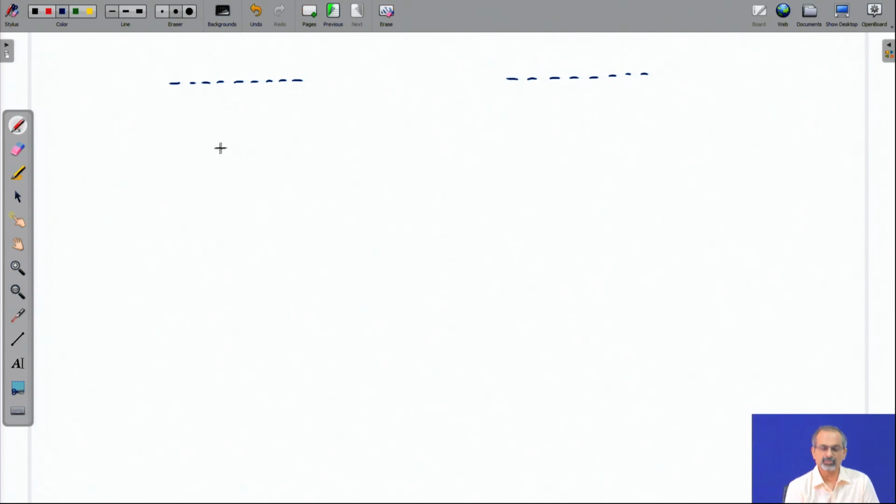We will revisit that concept once again, and we will now introduce the concept of symmetric airfoil in addition to the cambered airfoil that we already looked at. And then we will see how the pressure distribution on these airfoils would look when the angle of attack is 0 or otherwise. Now, in a symmetric airfoil, the camber line superposes on the chord line.